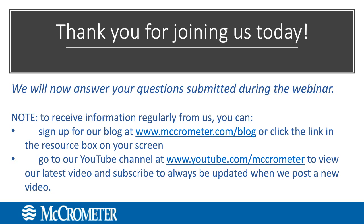Great, thank you. And the last question I have is, what is the accuracy of the orifice plate technology? So the accuracy of the orifice plate technology is covered in ISO 5167-1, the orifice plate, and similar to a VCone, you can get up to 0.5% accuracy on the orifice plate.